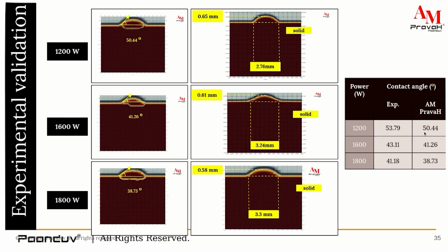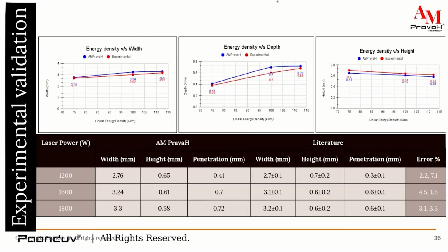Multiple times, the same solidified metal is melting again and again, and due to which these grains have become much larger and grain coarsening has happened, which effect you will see from the grain size evolution that the software generates. Similarly, you can cut different sections at different height, and you can see how the transformation of equiaxed grains happens from that to the columnar structures.